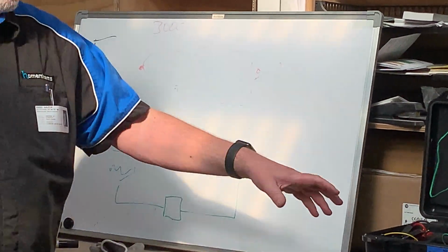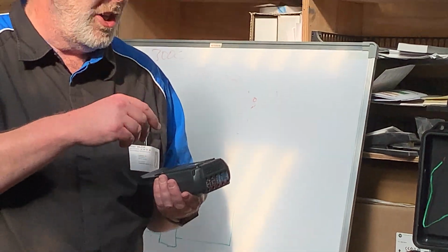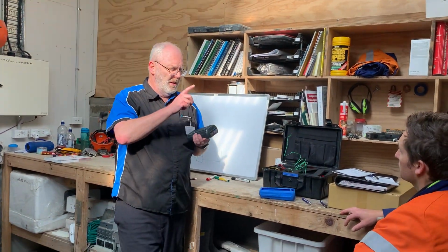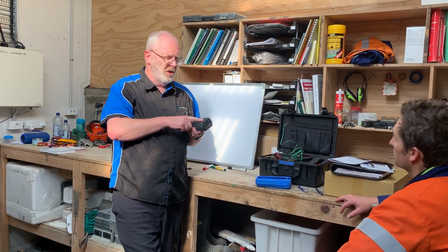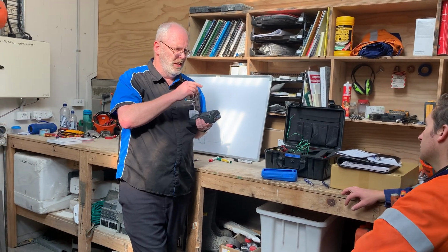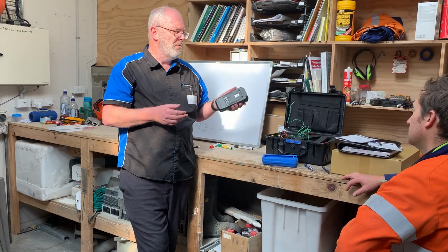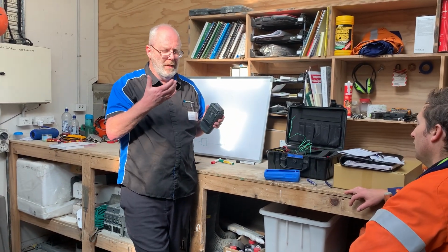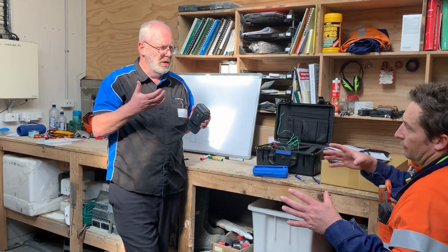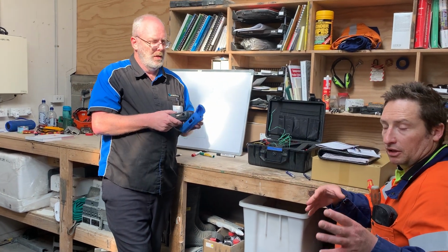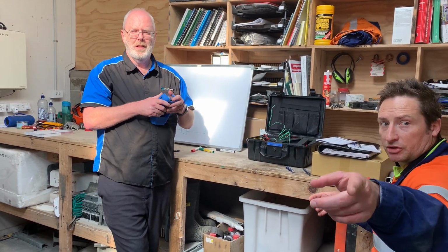The PRT is, and the cold junction, I actually conflated two points. The PRT is more for your calibration. The cold junction compensation is done electronically inside. You just don't need to worry about it. This is true of every thermocouple multimeter, every thermocouple device you measure.